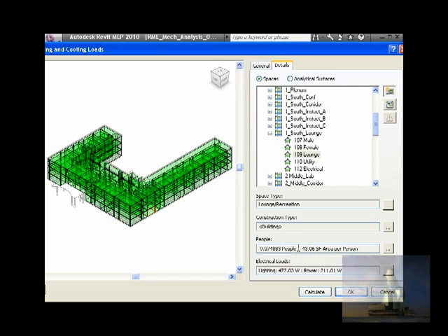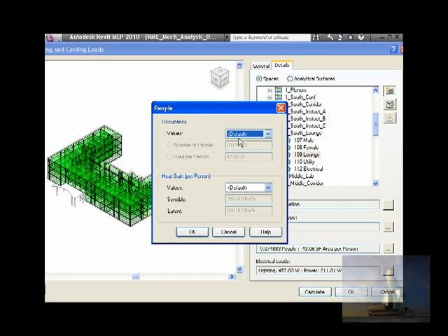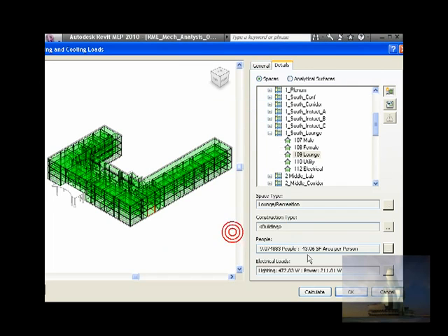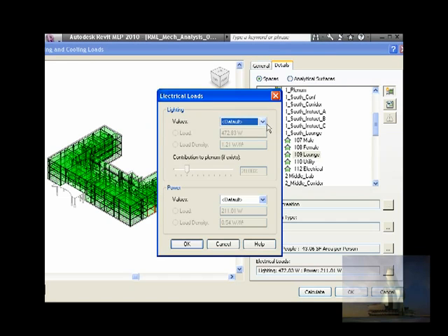And people, you could choose default values, and those are coming from the previous window we were just looking at. And the lighting, you could change it also. I have the default values, but I could say specify, and I could specify also the power. This is lighting and power, and I could specify, but I will leave the default because it's the setting I want to use right now.